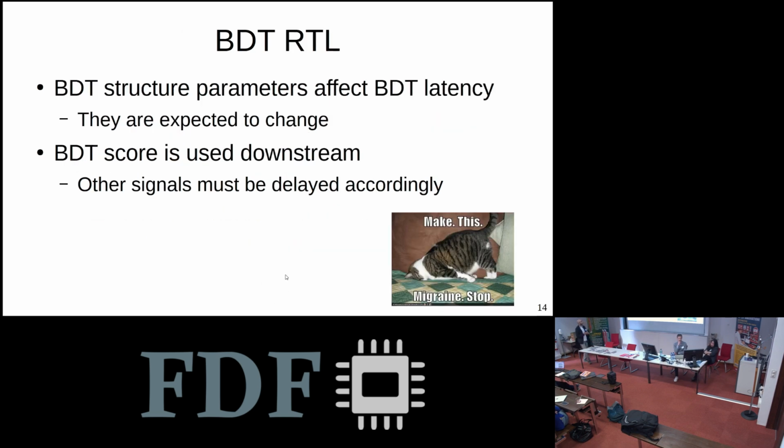And the BDT RTL as well, the structure parameters or the hyperparameters of the BDT might change. And that would affect, of course, the latency. And because the BDT score is used downstream, the other signals that are supposed to be ready at the same time should be delayed.